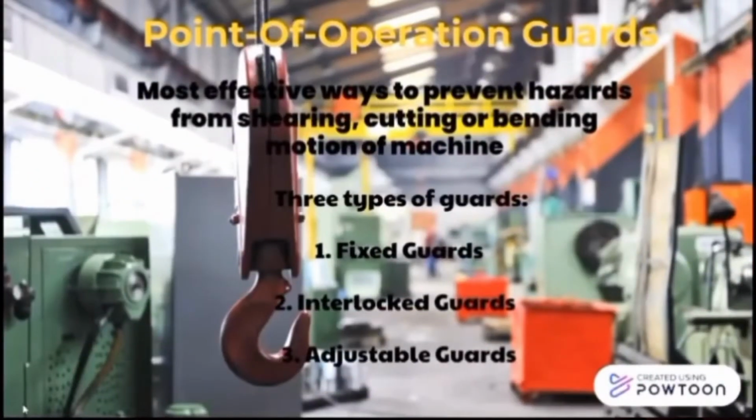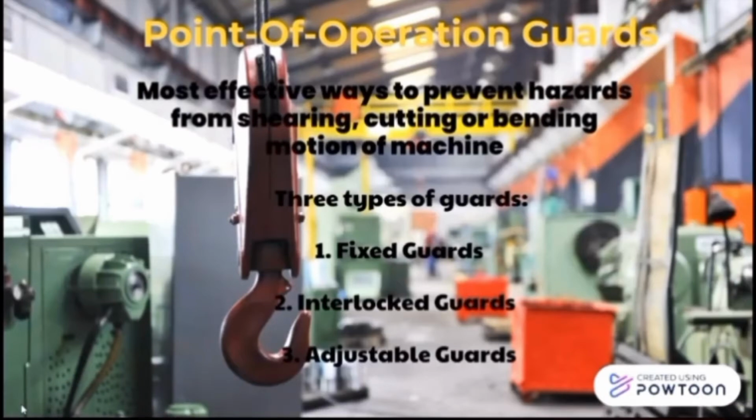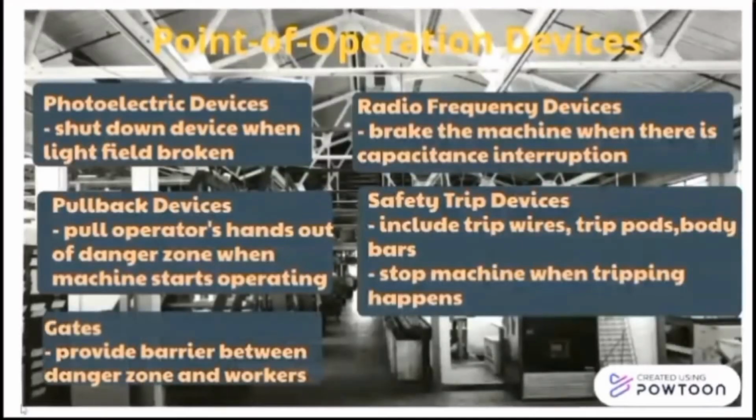Point of operation guards are the most effective ways to prevent hazards from shearing, cutting, or bending motion of machines. There are three types of guards: fixed guards, interlocked guards, and adjustable guards. Fixed guards are a permanent barrier between workers and the machinery, and they require regular maintenance. Interlocked guards shut down machines that are not securely in place and allow safe access during maintenance routines. And adjustable guards provide a barrier against a variety of different hazards.